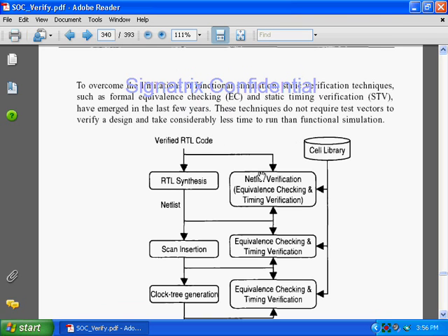With static verification, the tool, or STA tool, automatically performs the timing verification. It is less time consuming because we are not using extra labor to implement a test bench. We are simply using one tool, and it will tell you whether you have achieved functional verification fully or not. If you go with a static verification tool, most of the time you will get 100% coverage, whereas it is very difficult to achieve 100% coverage in functional simulation with the help of test benches.